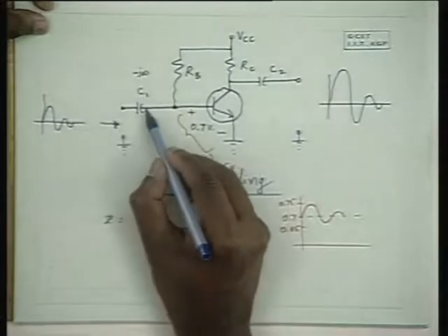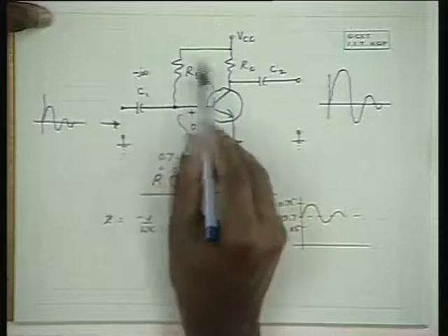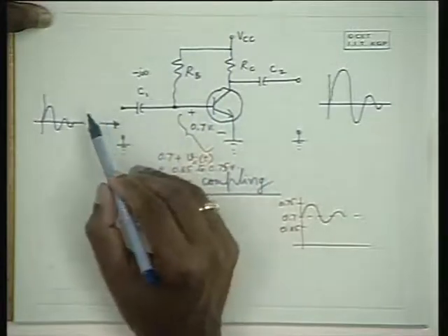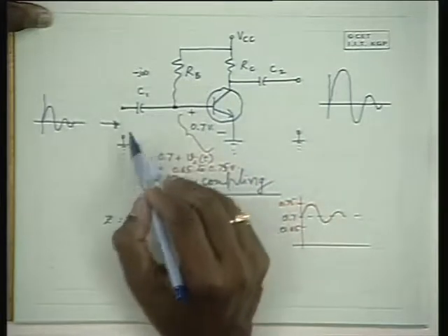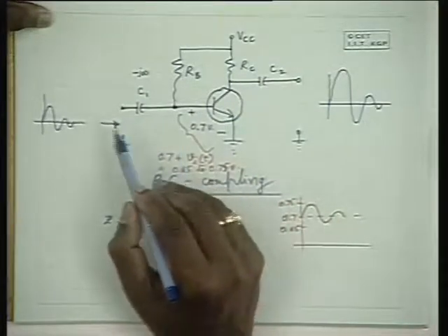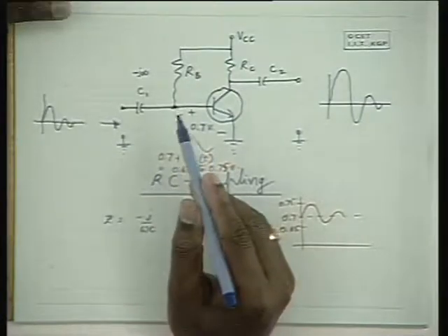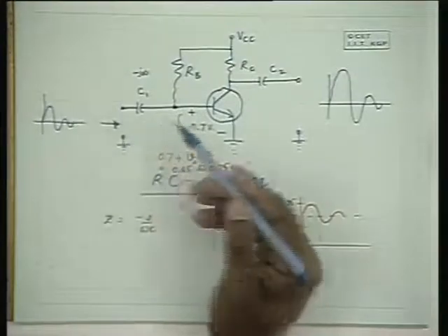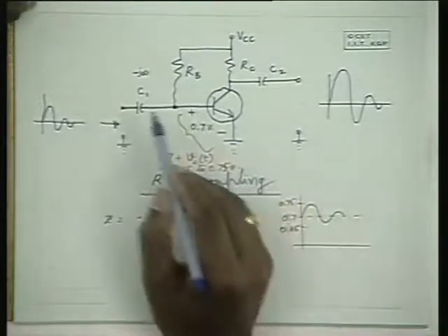And since the objective of the coupling capacitor is to block only the DC and to act almost like a short circuit to the alternating components, the capacitance should be as large as possible. For audio signals, the frequency range is from a few tens of hertz onwards.